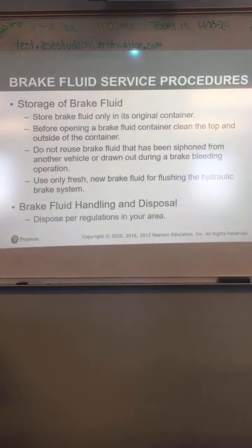Another topic is storage of the brake fluid. Remember, keep it only in its original container, which should be sealed. Don't reuse brake fluid that's been siphoned from another vehicle. Only use fresh, new brake fluid for flushing the brake system.